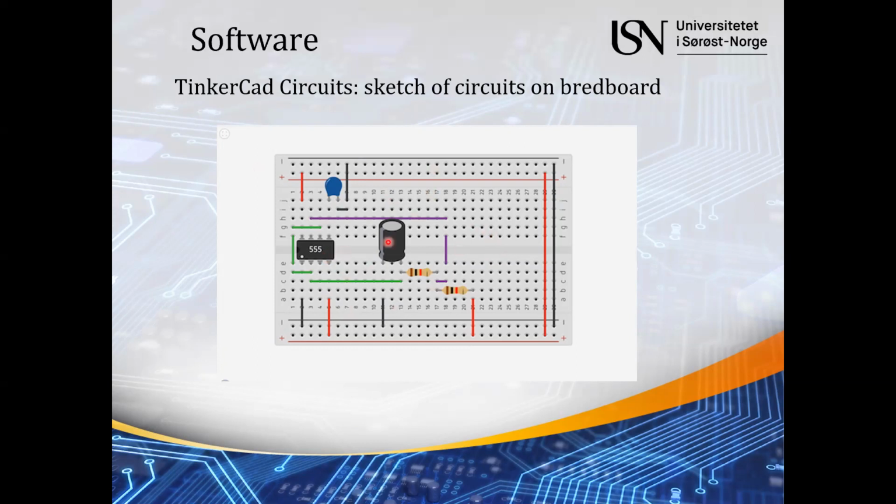However, when you build on the breadboard, you need to know very well how to connect the wires. For example, here, this line represents a wire. So you need to know very well how to connect them. So it's always nice to go to the lab with a paper with this picture, which shows how you think you should connect the components in the circuit.